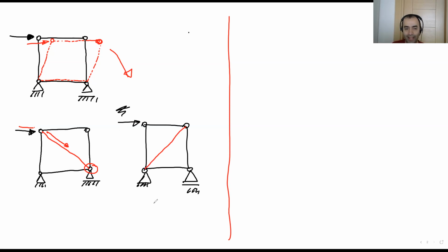Again, we split the system into 2 triangles. It works again. The load basically goes there. This point wants to go in the lateral direction, and there will be tension on this bracing and it transfers all these loads to this support. So at the end of the day, what you need to know here is that we have to divide our system into triangles.